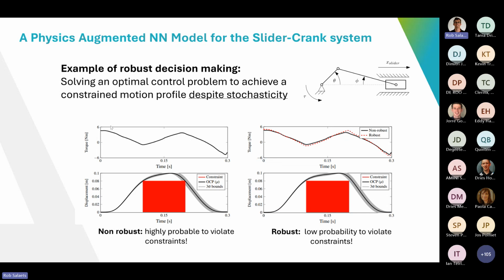So let's think again about, let's say, a weaving loom. We have to make some kind of displacement motion, and we need to find the torque profile we need to apply to achieve this motion. And we want to go as fast as possible, but we cannot enter the red square. So we need to be at a certain time, at a certain displacement, and then we need to be above that displacement also until a certain time. So we need to be above the red square.